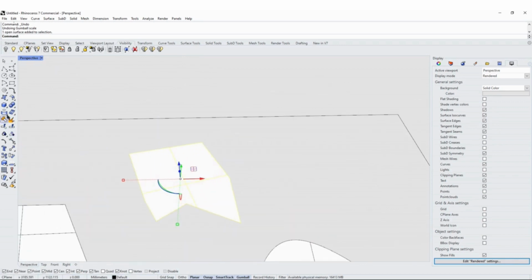I select the element that I would like to, I go right over here, in this tool over here, but then I click on the side. And there's going to be a duplicate border command. Click on that, and now you can see that we have a yellow highlighted outline. So now we have back the outline curve of this shape.